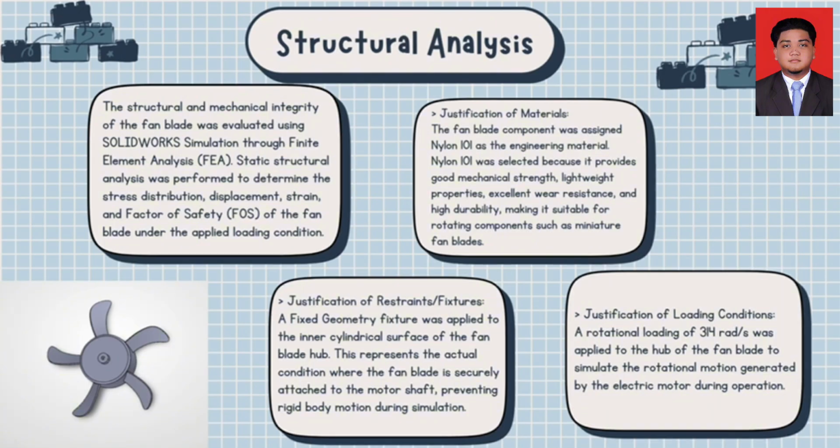So now I want to continue the presentation for structural analysis. The structural analysis and mechanical integrity of the fan blade was evaluated using SolidWorks simulation through finite element analysis. Static structural analysis was performed to determine the stress distribution, displacement, strain and factor of safety of the fan blade under the applied loading condition.